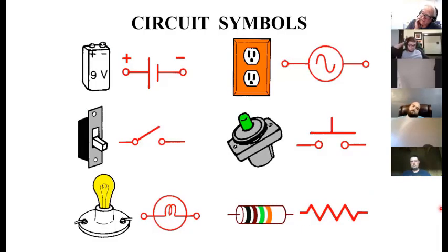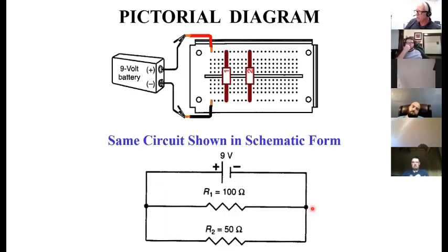Some common schematic symbols. It doesn't take too much imagination to see how these came up. This is a switch that you're going to just throw into place. This is the push button switch. This is a breadboard. We'll talk more about breadboards later, and you'll be using them in the lab. But the way this works, here's my voltage supply, a 9-volt battery, and I'm hooking up positive to this hole. All these holes along this way are common. When I say they're common, I mean they're all touching one another. Whenever you talk about a circuit common, that means where components come together to a single point.